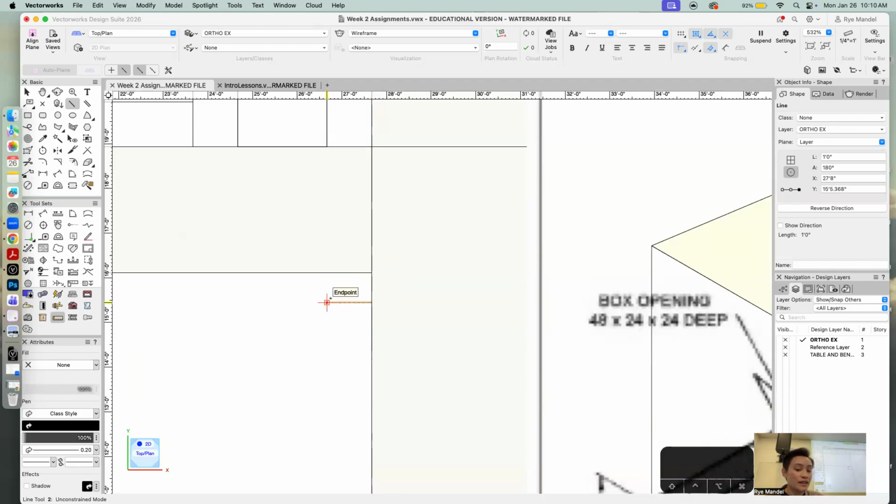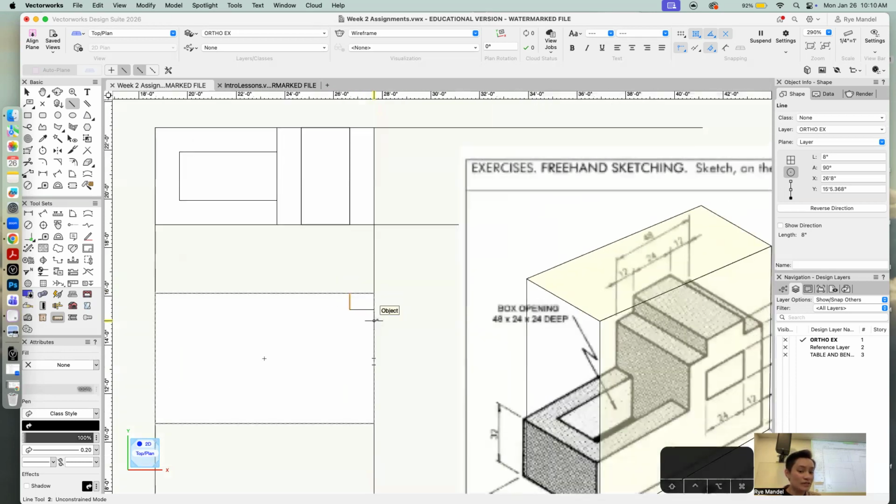So all of these points that I'm doing is basically going through and snapping everything in order to make these lines, so I know that's going to be 8 inches down from somewhere. It always has to have a reference point from somewhere. The next point I'm gonna do the other way, just going down. This one's 24 inches across, so I can take it from my ground point, my top view, and then go over and create another one that is 8 inches. And then I can go over again, and this one's 12 inches. Shift, enter, and then it's there.